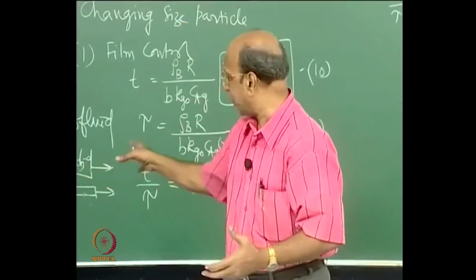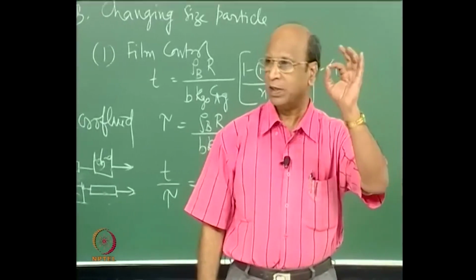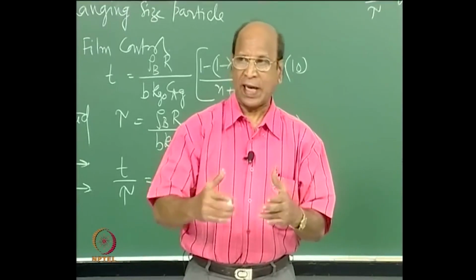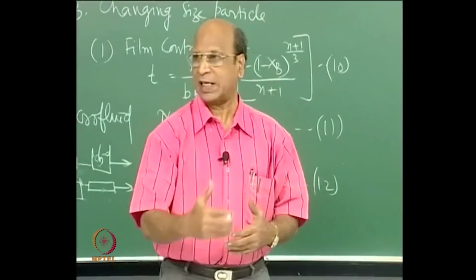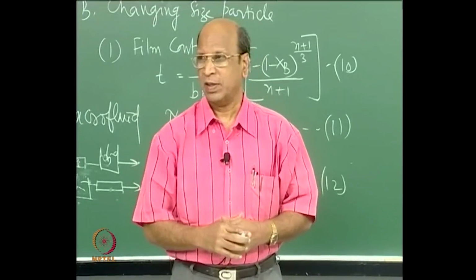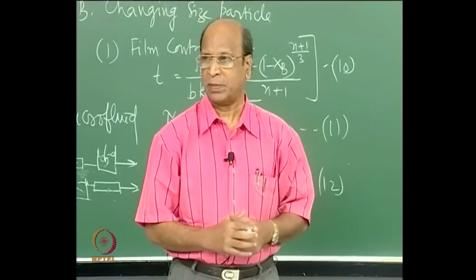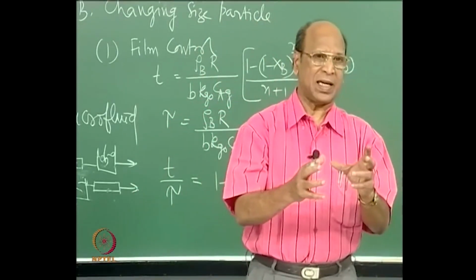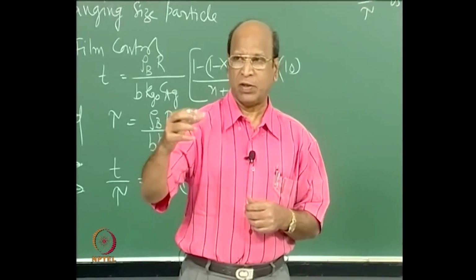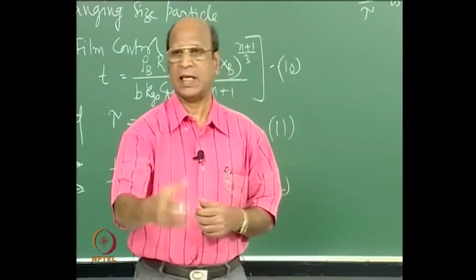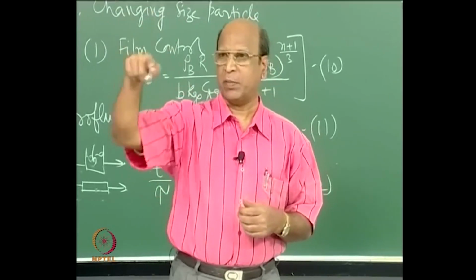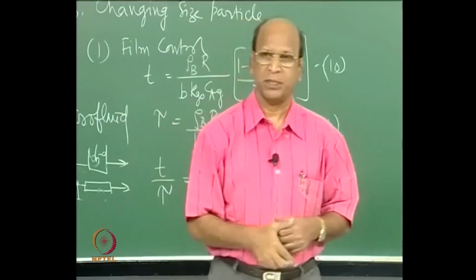If I take an ideal mixed flow reactor, I have a specific RTD, because I am telling mixed flow. So, when I have a specific mixed flow reactor, I know definitely my RTD; the reverse is not possible. That is also a wonderful point which we discussed last time. Given a reactor, you know definitely what the RTD is. Here, if I have a mixed flow reactor, then the equation is E(t) equal to e to the power minus t by t bar, divided by t bar.